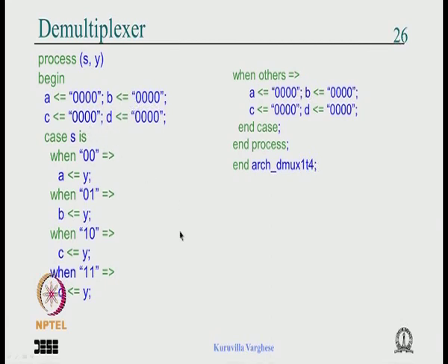So the synthesis tool will look at the code and infer this kind of behavior. There should not be a problem, but I warned you not to take this kind of behavior to an extreme. Do not play with delta cycles and all kinds of initialization, hoping that your reasoning would be understood by the synthesis tool. But definitely the tools are getting smarter.